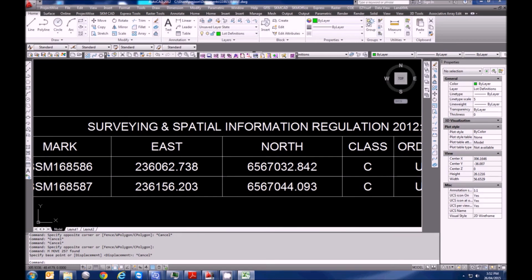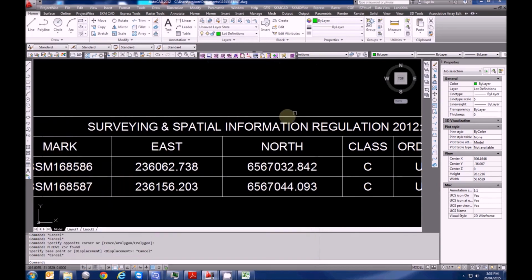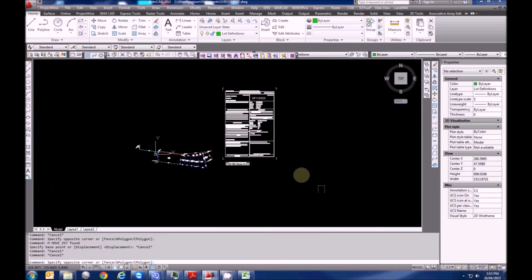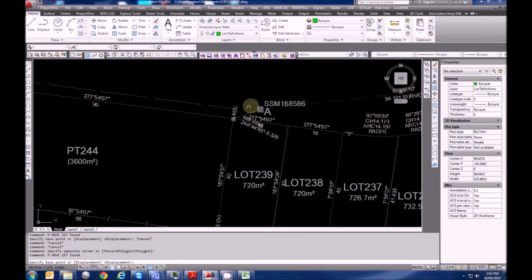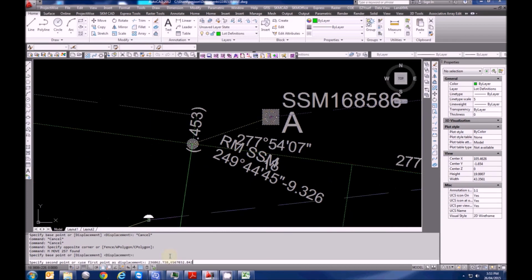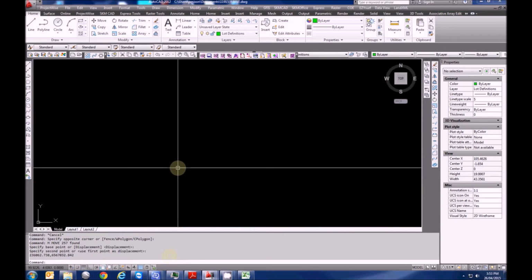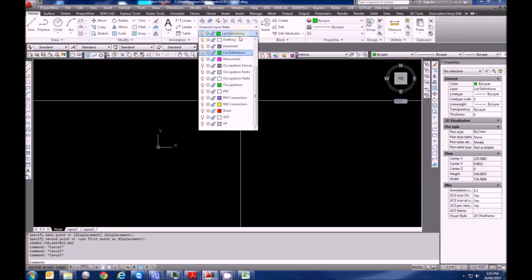Our A mark is 386, so I'll just put it in the notepad document. Paste that there, grab the coordinates that we need, and what we want to do is move the entire job from our assumed datum where we started, from this point, to that coordinate that I just grabbed. So now we're up in the correct coordinate system. There must be something turned off, is there? No.